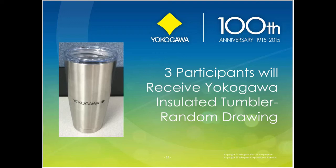Another question, what type of application recommends RTD 3 wires? There are actually two questions, 3 wires versus 4 wires. RTDs are good for a lot of applications. It's hard to say, it just depends on the accuracy that you need. A 4 wire is going to be the most accurate, but typically in industry, 3 wires are the most common. So there's not a lot of need for 4 wires in industry. That's more of a laboratory requirement. Yeah, it depends on the lead wire length too.